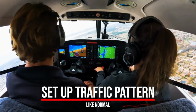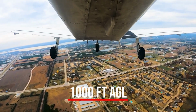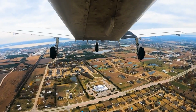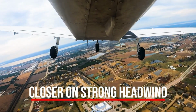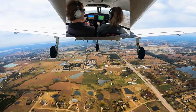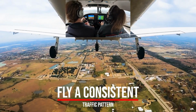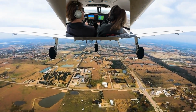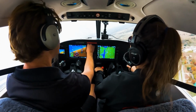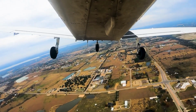The best aid in perfecting the ability to judge height above this altitude is through the indications of the altimeter and associating them with the general appearance of the Earth. The judgment of altitude in feet, hundreds of feet, or thousands of feet is not as important as the ability to estimate gliding angle and its resultant distance. Regardless of altitude, a pilot who knows the normal glide angle of the airplane can estimate, with reasonable accuracy, the approximate spot along a given ground path at which the airplane will land. A pilot who has the ability to accurately estimate altitude can also judge how much maneuvering is possible and safe during the glide, which is important to the choice of landing areas in an actual emergency.